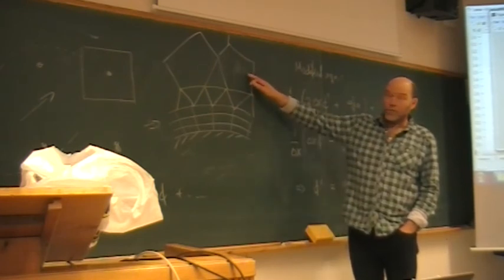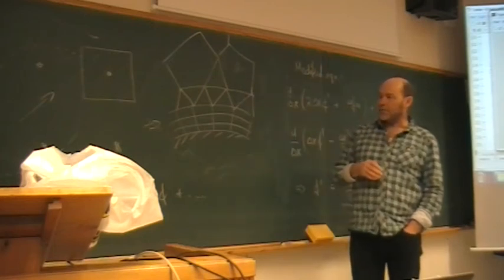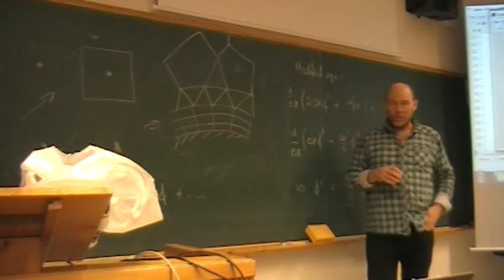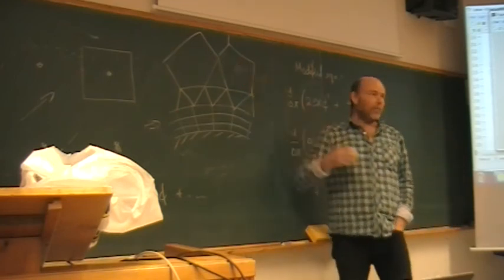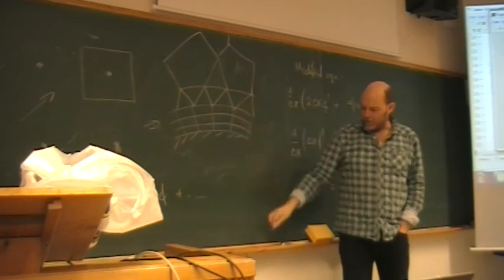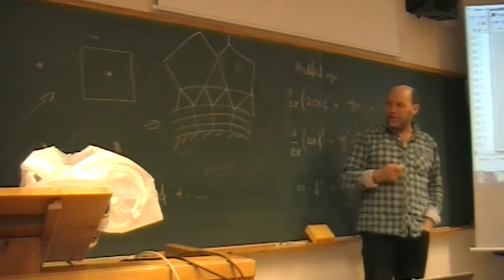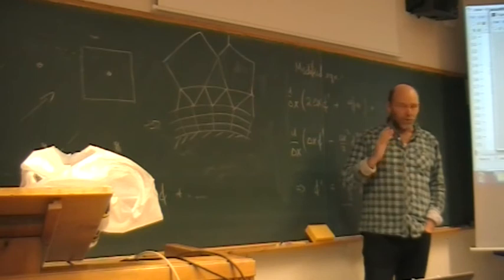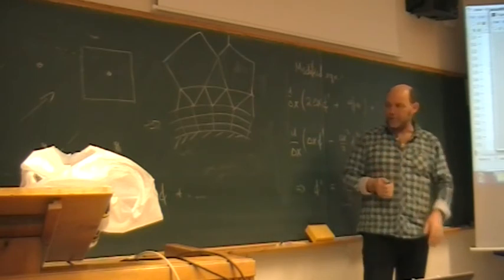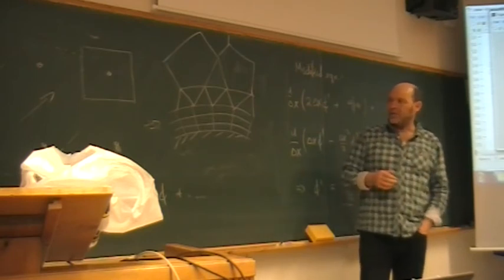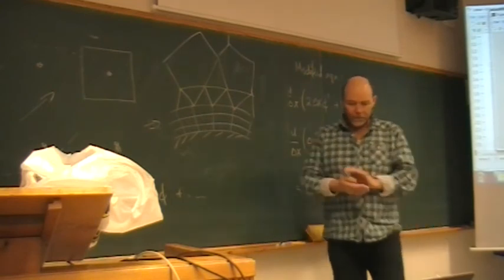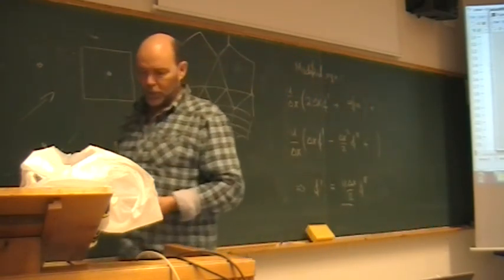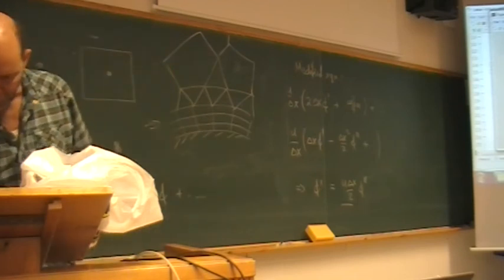An advantage, of course, with unstructured mesh is that you can handle any complex geometry, and also you can stretch your mesh using large cells where nothing important happens, focusing on areas of interest, close to walls, in small nozzles, in a jet, things like that. So we will have a little bit of that later when we jump to finite volume.